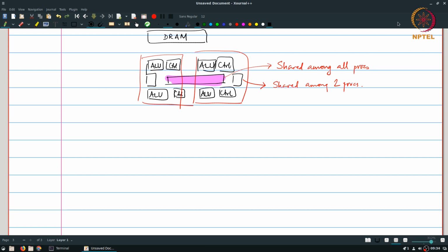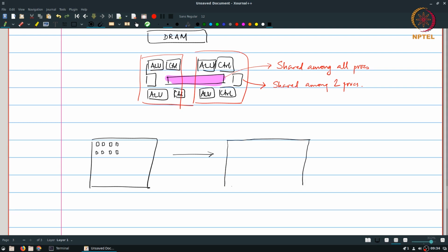So how do we make use of the observation that image processing typically has a very large amount of parallelism? In other words, each pixel could potentially be processed independently, or at least simultaneously with a lot of other pixels. So the architecture should also reflect that kind of structure. The architecture that the GPU architects came up with looked similar to the pixel array that exists on an image. So rather than having large ALUs, large control units with some amount of shared cache and an interface to DRAM, the structure that was adopted was something more like this.